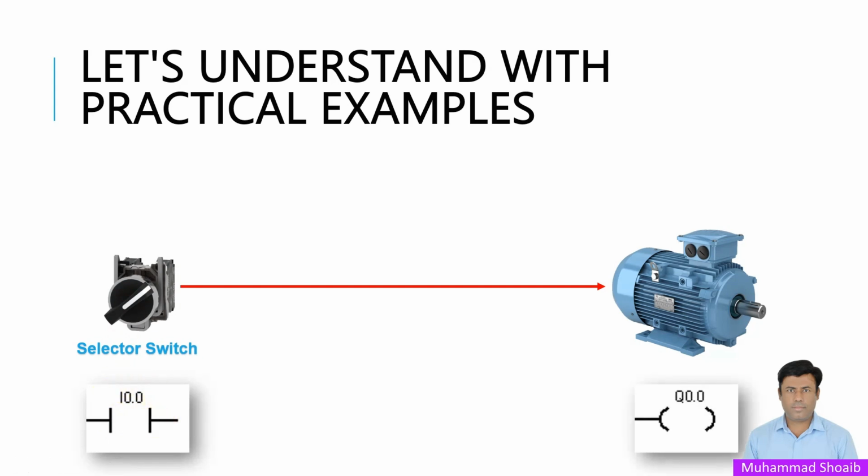Then we'll take an output contact or coil, that once this output coil is on, it will turn on our PLC output relay, and that will energize the relay and magnetic contactor, and the motor will turn on. So in PLC programming, if we want to turn on a motor with a selector switch, we have to take one NO contact and the output contact, and we have to connect them with each other.